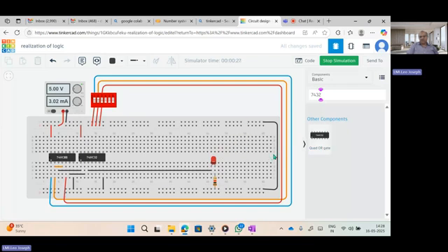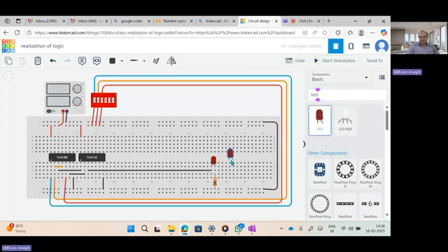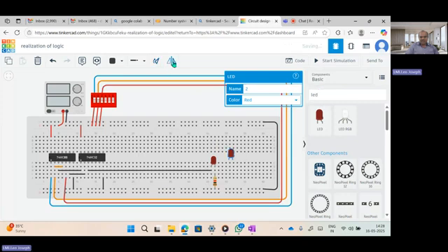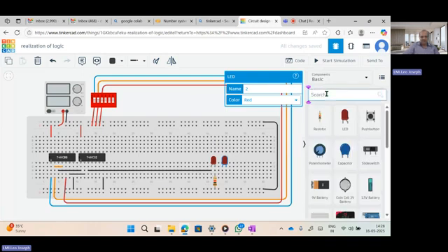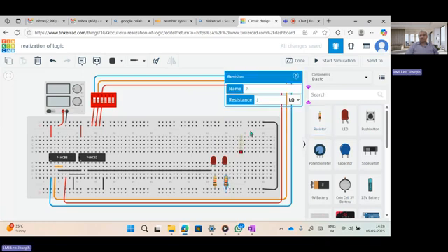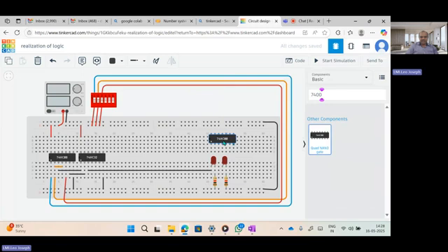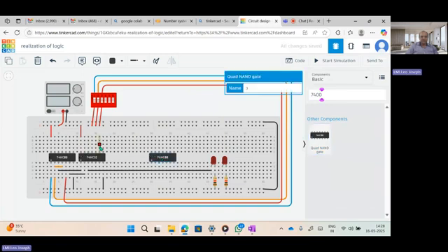So the same setup I am going to do with the help of another LED and resistor. Here I am taking one LED and I am just rotating, shifting this, and I am going to give the resistor. Why I am doing this is I am going to do the same realization with the help of NAND gate, that is 7400. This is the NAND gate. Single IC. Two ICs are working now. Now with a single IC I am going to realize the same operation.